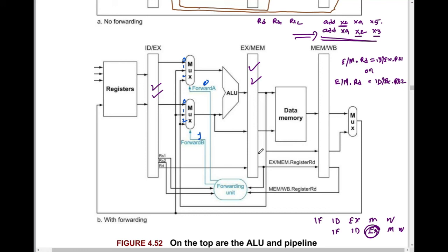So if you want to check the condition I'm describing, that if the RS1 or RS2 of the second instruction depends on the RD of the first instruction, then this type of forwarding should be there, meaning forward A should be 0, right? We are checking the same thing here. See, XMEM is this register particularly. If the RD result stored in this register is equal to RS1 stored here, or equal to RS2 stored here in IDEX, then there should be forwarding.